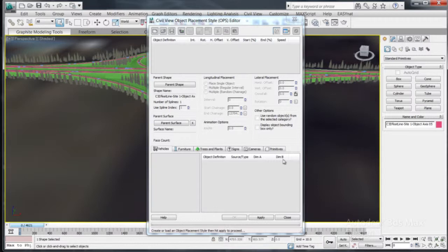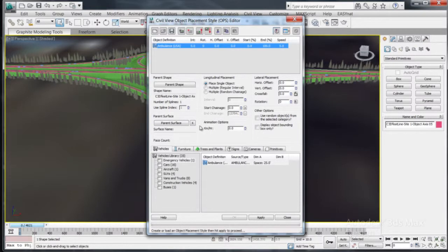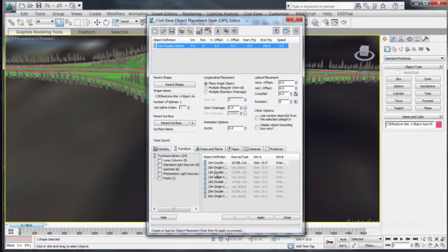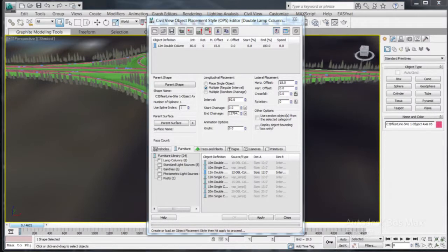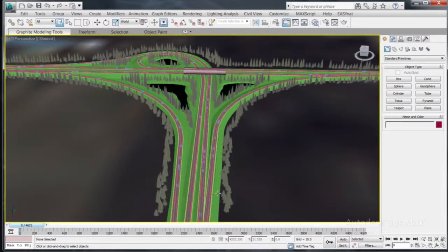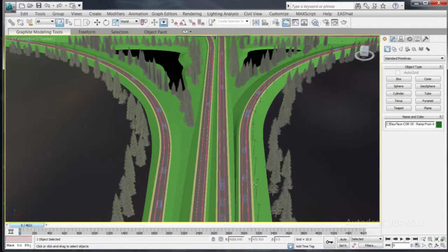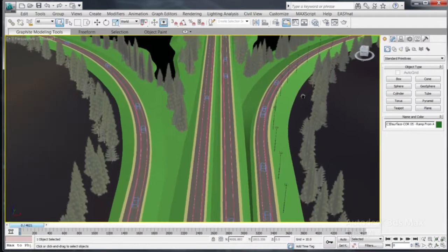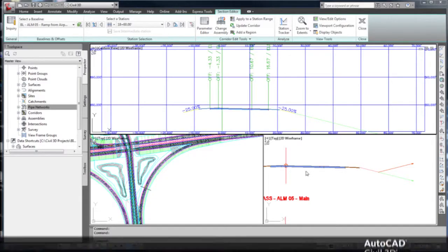The geometry for these placed objects is derived from a customizable object library in Civil View. Once again, by default, placed objects have a permanent dependence on an imported alignment or feature line from Civil 3D. When a design change occurs, the locations of all associated placed objects will update automatically. In order to effectively utilize visualizations as part of the design process, it is essential that a visualization be able to react to frequent design changes made in Civil 3D.